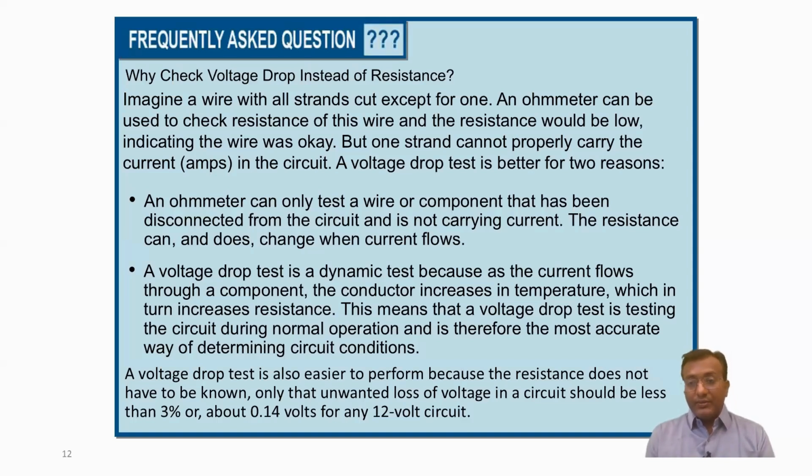Now, about testing of voltage drops in automobile circuits, how is it beneficial for us? A voltage drop test is often more practical than resistance testing because it measures voltage loss directly during operation. For instance, testing a particularly damaged wire might show low resistance, but under current flow, it reveals voltage drop due to heat, indicating a problem in the system.